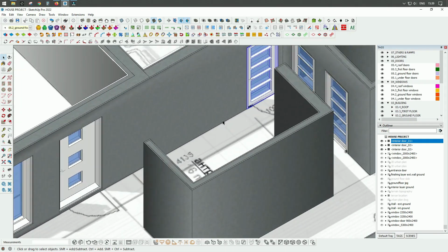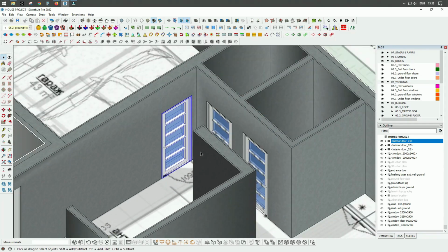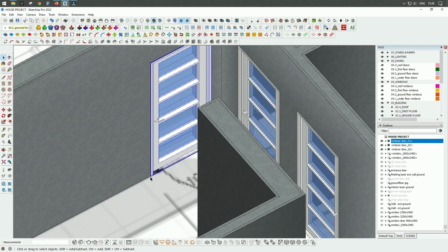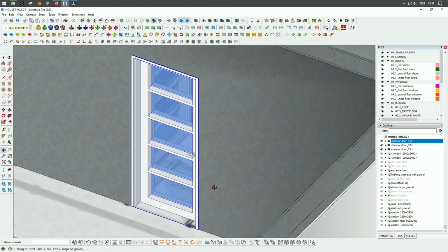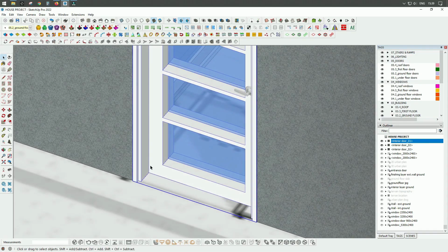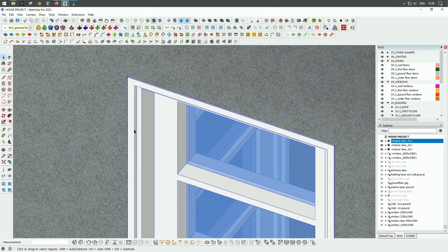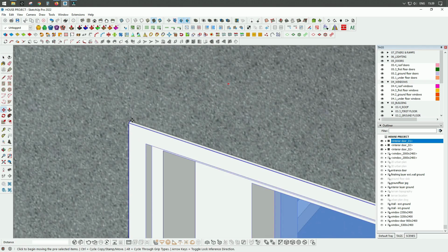thick. And as you can see, I made a mistake here with these interior walls, because they should be 75 millimeters above the zero level, and I placed these walls, these doors, exactly at level 0, so I have to move them 75 millimeters above level 0.